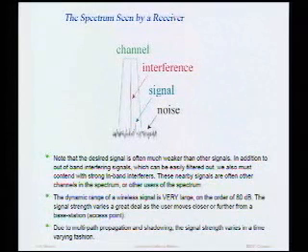The other issue with just using an amplifier is noise. In many situations, the signal is not much bigger than the noise. And so if we just go into 140 and basically design an amplifier, you'll find out that it might actually be a noise amplifier. It might actually make the noise bigger than the signal that you're trying to amplify. So pretty soon, the signal that you're trying to detect is lost in the noise. And this noise is ever present. We can't get rid of it. It's a part of nature. It's a very natural phenomenon.